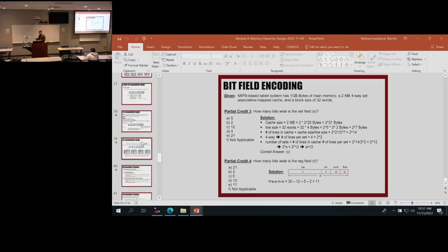These lines are the block slices that we can talk about. This is connected to the memory. We have different bit cells here and so on. So this is going to be, for example, the bit line, or the word line. This word line is going to activate this entire path. Then you have another decoder here that chooses, for example, the bits, and it says, okay, this byte is the byte that I care about. So you have a bunch of decoders all around the peripheral circuitry of the memory that is choosing from this. But the problem here is that this is such a huge decoder if you want to go to the main memory.